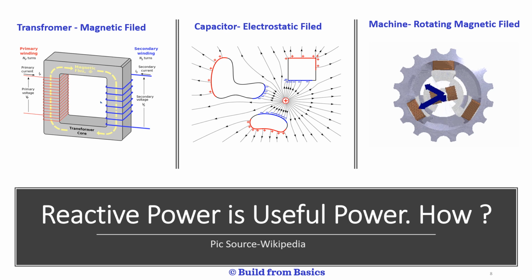However, there is a need for reactive power compensation in the power system to balance the reactive power consumption and production. Instead of transmitting the reactive power from generating stations to the load centers, because it results in additional losses and voltage drop, what you can do is generate reactive power at the places of its requirement. This avoids transmitting through the lines, and this is called reactive power control. Reactive power control basically helps in reducing the losses in the lines due to the additional current flowing through the lines, and also the voltage drop, as I mentioned before.